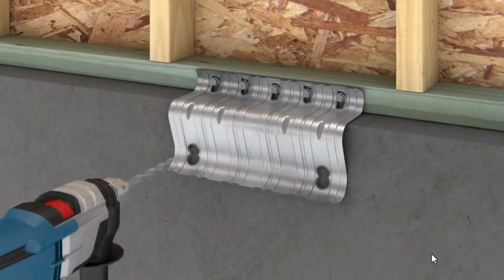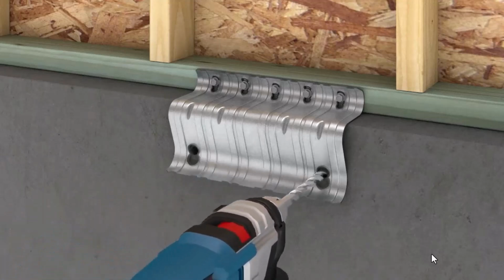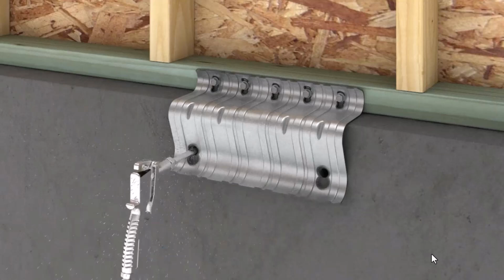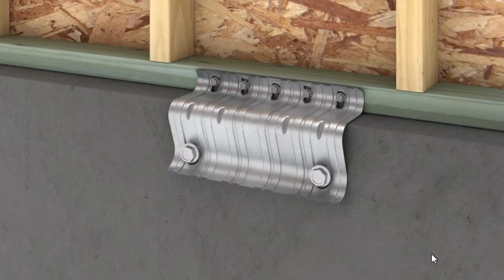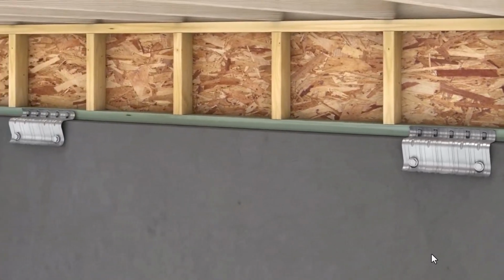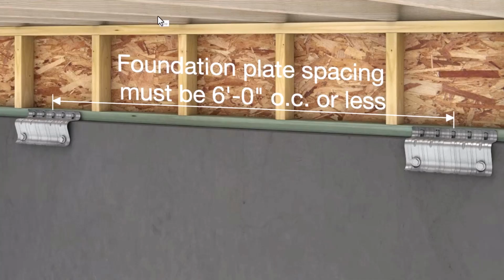With a rotary hammer and a ½ inch carbide bit, use the URFP as a guide to drill 2 level anchor holes. Clean out the holes using compressed air. With a 3/4 inch hex driver and impact wrench, install both Simpson Strong-Tie Titan HD heavy-duty anchor screws to complete the installation. Repeat the process for all remaining plates. For spacing requirements, follow your local building code.